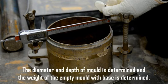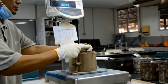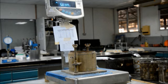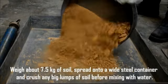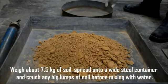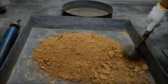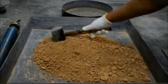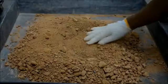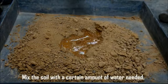Procedure. The diameter and depth of the mold is determined, and the weight of the empty mold with base is determined. Weigh about 7.5 kg of soil, spread onto a wide steel container and crush any big lumps of soil, before mixing with water. Mix the soil with the certain amount of water needed.